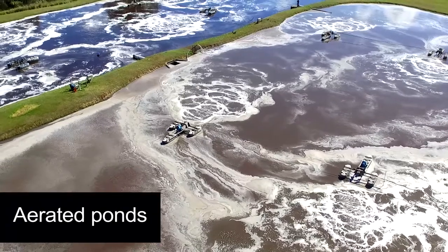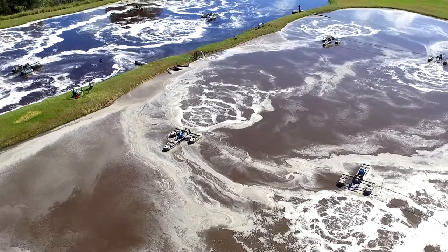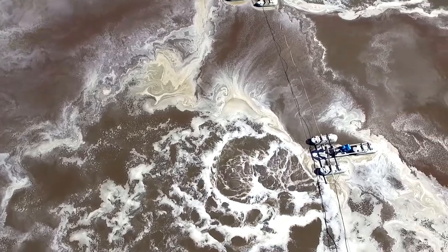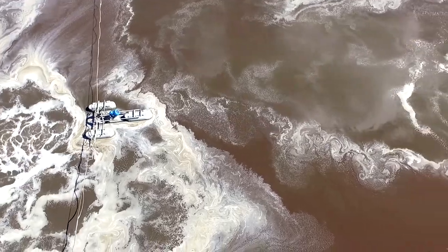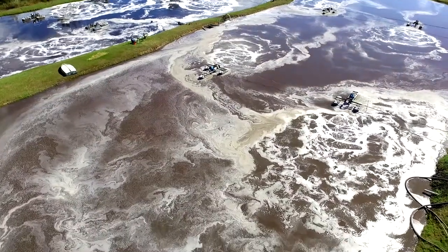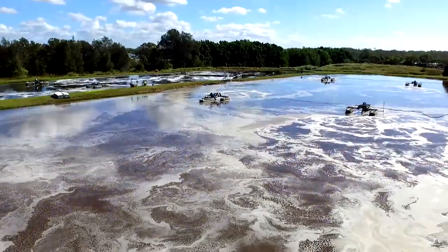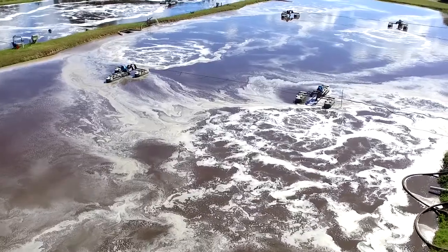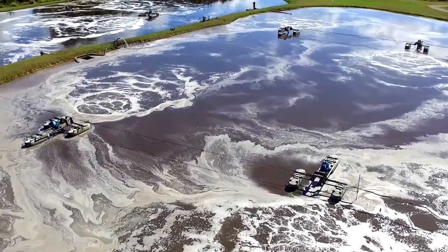Aerated ponds are increasingly common and can overcome the main limit of facultative ponds, which is the ability to add enough oxygen to keep an aerobic top layer. Rather than depending on algae to oxygenate the top layer in aerated ponds, oxygen is provided by mechanical floating surface aerators or submerged blower aerated systems such as air stones. Sometimes only enough air is supplied to ensure the top layer is kept aerobic, or enough air is supplied to aerate the entire volume of the pond so there is no anaerobic layer. This is called a completely mixed pond and demands higher levels of power but less land than facultative ponds.